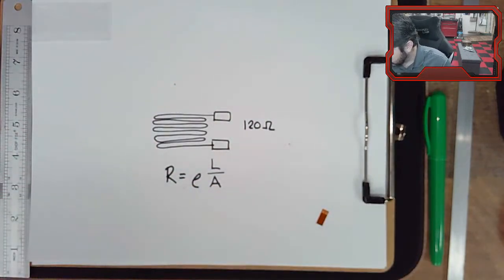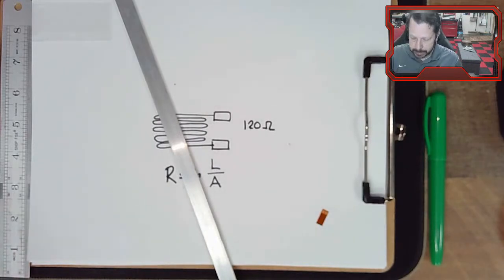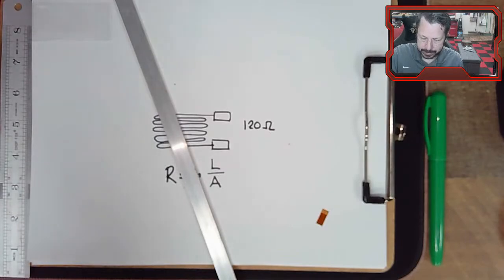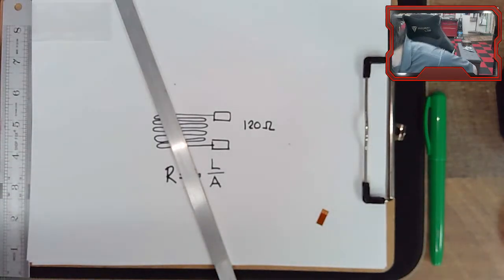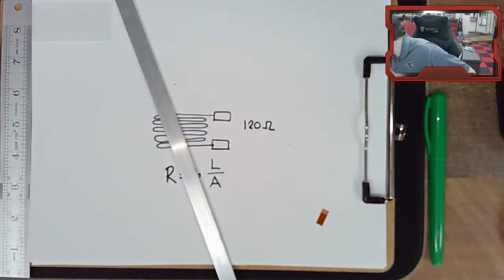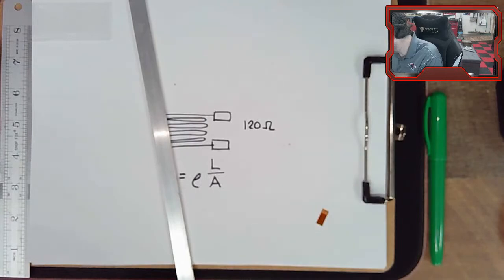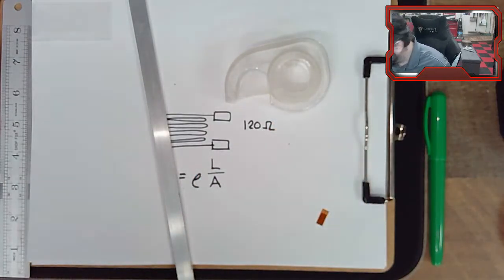All right. So to get this thing on, there are very specific ways to do this, but obviously I'm not in a lab setting right now, so we're going to be a little less specific. But you should have a couple of things. A little aluminum bar to put your strain gauge on. Some tape is going to help. It's not totally necessary, but it will help.